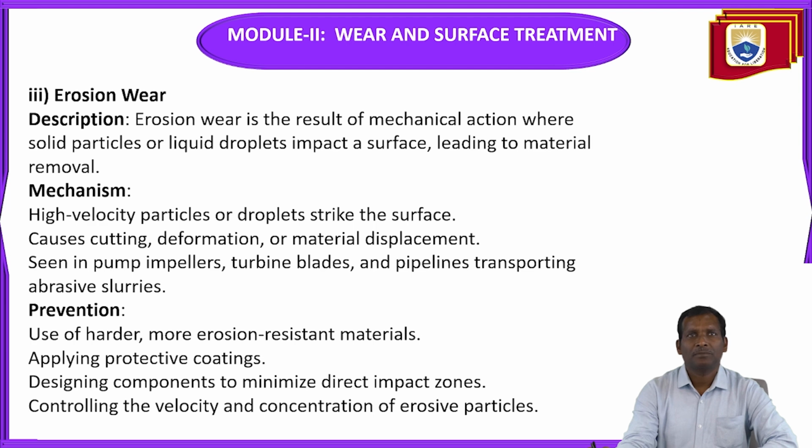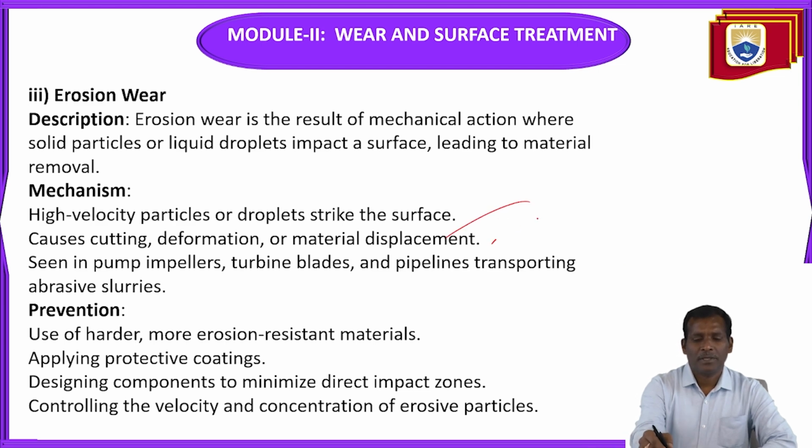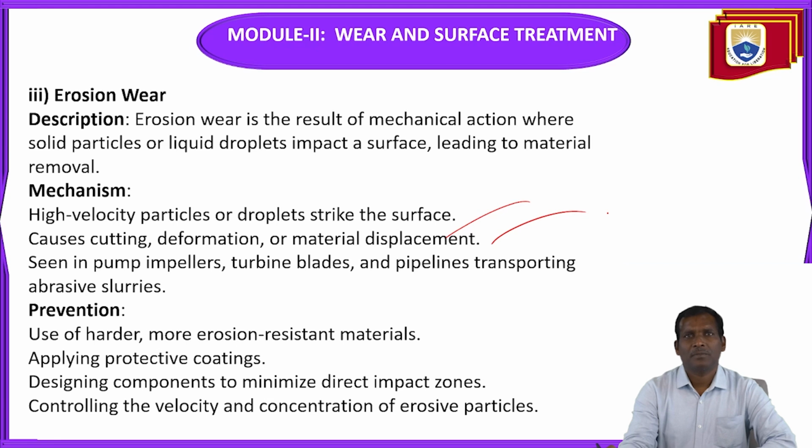Next, erosion wear. This one also we have studied. Erosion wear is the result of mechanical action where solid particles or liquid droplets impact a surface, leading to material removal. The mechanism is high velocity particles or droplets strike the surface, causing cutting, deformation, or material displacement.